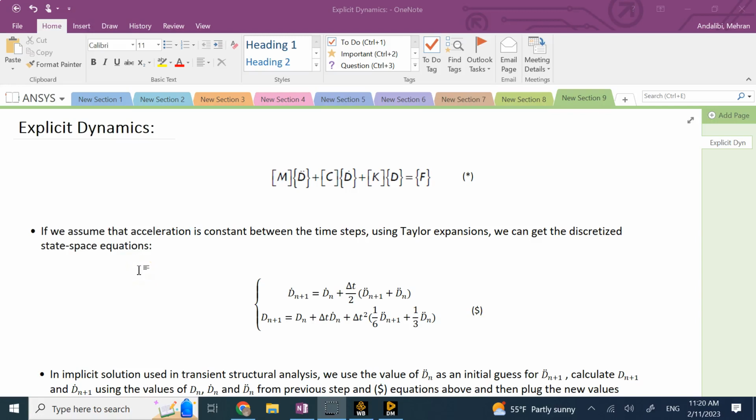Hello everyone. In this video we are going to talk about explicit dynamics simulations in ANSYS. So explicit dynamics is useful when the changes are very fast and the whole simulation happens in a very short time: milliseconds, microseconds, nanoseconds, like impact, collisions, drops, and so on, drop tests.